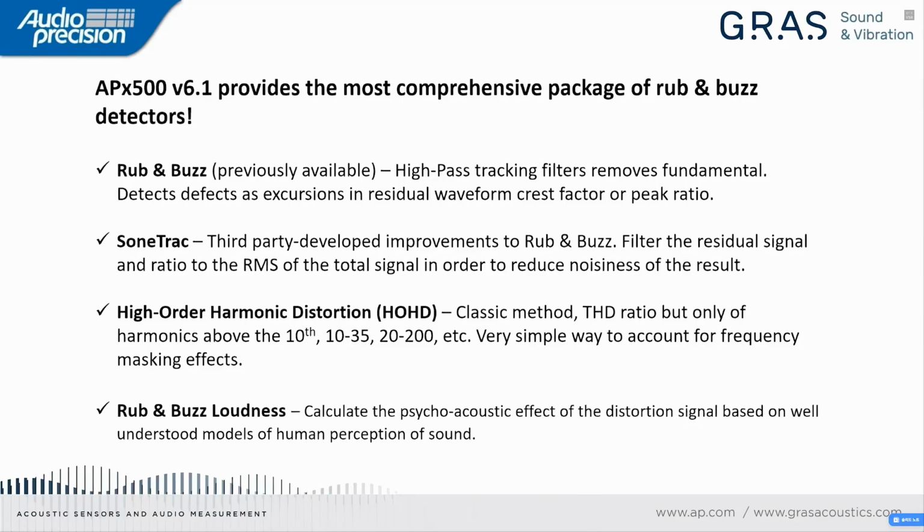And then we have rub and buzz loudness. This calculates the psychoacoustic effect of the distortion signal based on well understood models of human perception of sound. And this is possibly the most representative detector of that annoying sound that we hear when there is rub and buzz artifacts.